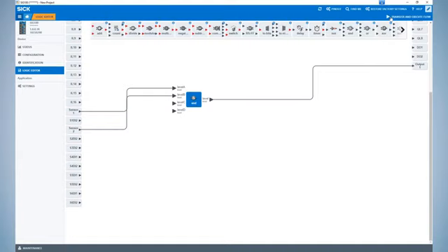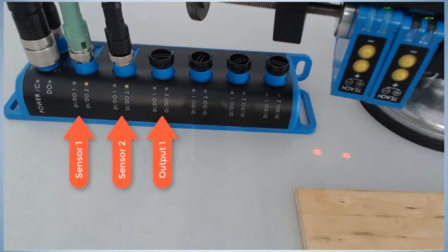Once all connections are established, click the Transfer and Execute Flow button to transfer the logic to the SIG100. An error message will appear if there are any improper or missing connections. The notification area will indicate a successful transfer. Note that clicking on a notification will make it disappear.